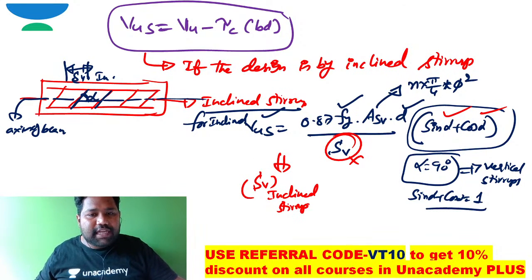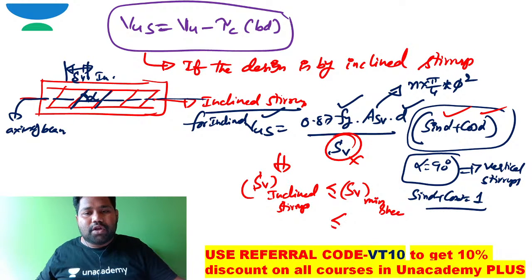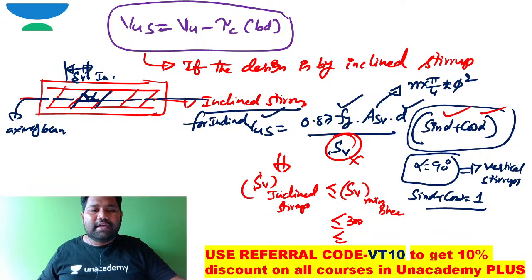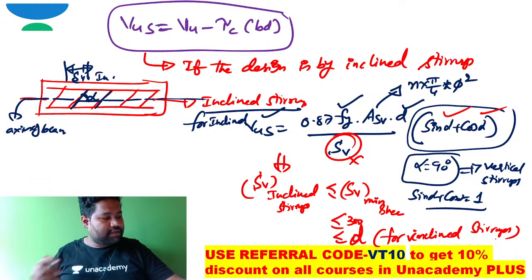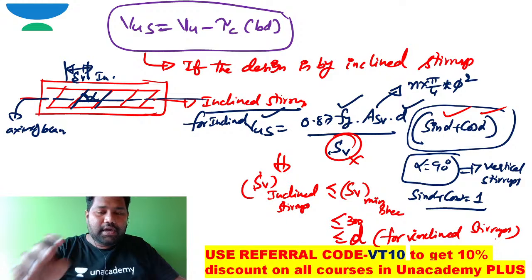The spacing of these inclined stirrups should always be less than or equal to the spacing of minimum shear reinforcement. The spacing should always be less than or equal to 300 millimeter, and less than or equal to 1 times d, the effective depth, for inclined stirrups. This is how we can deal with this.